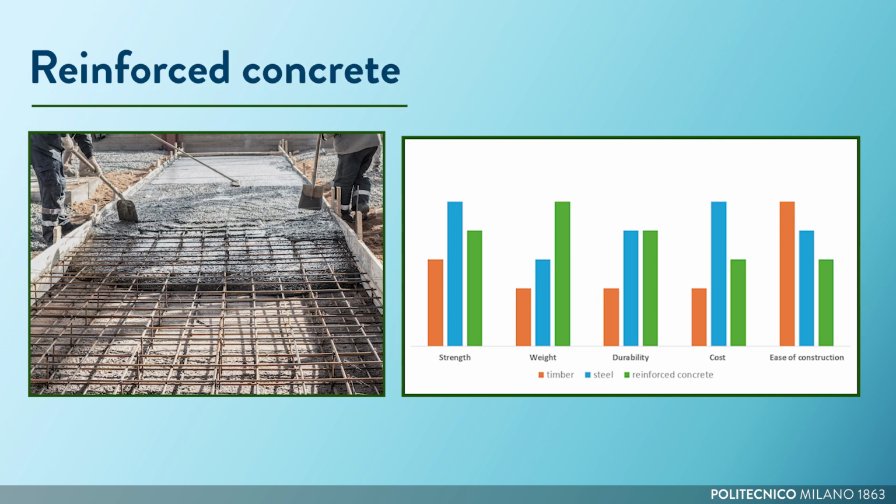Reinforced concrete is a popular choice for small river bridges due to its strength and durability. Concrete can be cast into various shapes, allowing the use of different bridge schemes. Thanks to the steel reinforcement, it provides excellent load-bearing capacity and ductility. Proper mixing techniques and detailing are crucial to ensure bridge durability and long-term performance.